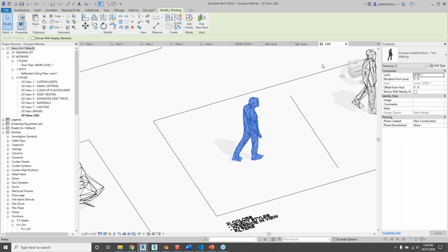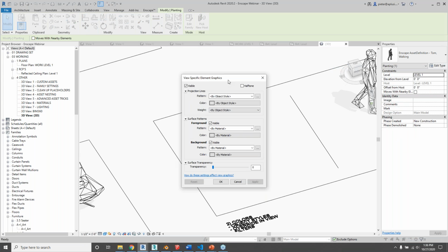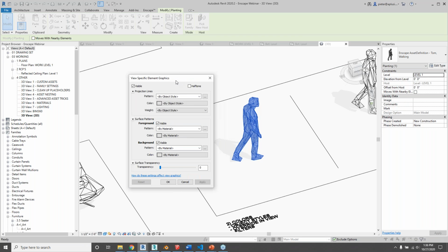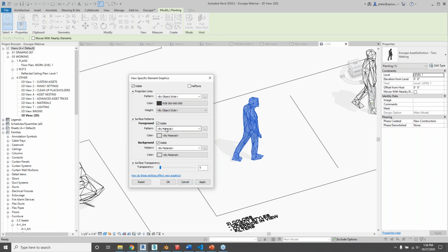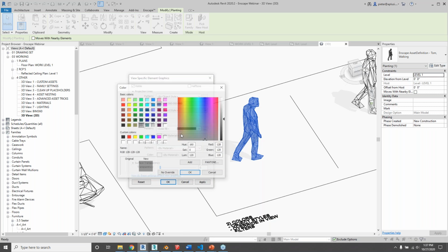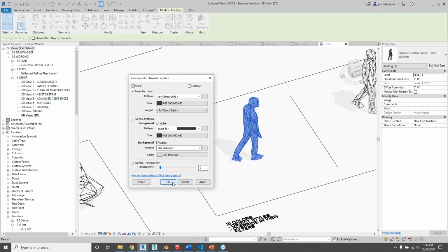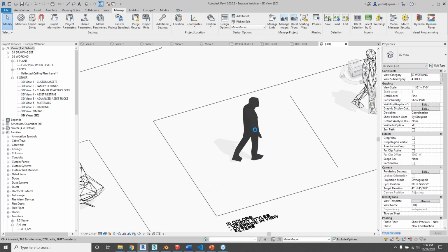And then what we want to do here is pick the same color for the lines as for the solid pattern that we're going to assign. So let's do a color like 60, 60, 60, which is something that I like. And then here we do solid fill also for 60, 60, 60. So we're going to have the edges solid 60, 60, 60, and also a solid pattern with that same color on it. And so if we do that, we get something that looks more,